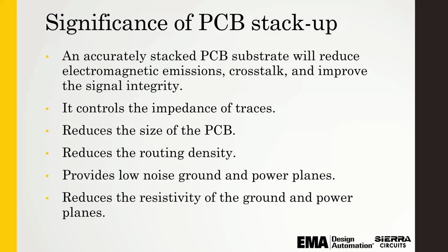And the planes also provide signal return paths for the varying and high frequency signals, and it helps considerably reduce the noise and signal crosstalk. So those carefully placed planes are really important to get good signal integrity.